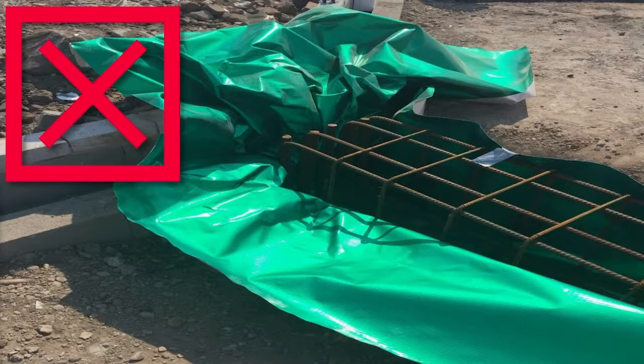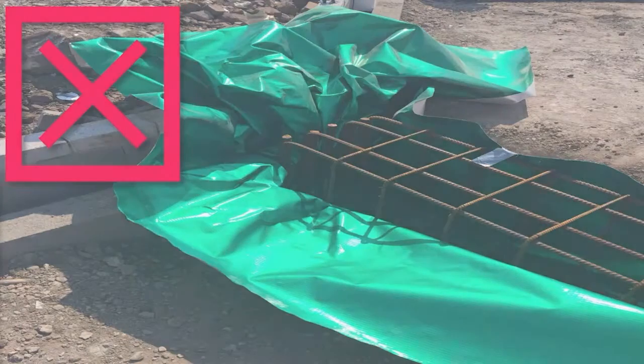In this case, we can see the rebar laid directly onto the membrane with no protection fleece or board used. The fleece is not only important to prevent direct puncturing of the membrane, but also to prevent damage from cutting using saws and grinders. These processes produce large amounts of sparks which, if they contact the membrane, can melt holes and cause significant damage. So while a small increase in cost per square metre to specify a fleece or protection board may seem unnecessary, the effect it can have in reducing remediation costs and delays is more than worth it in most cases.